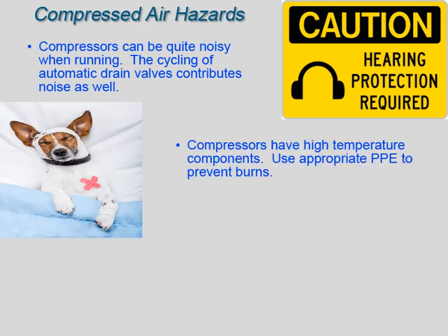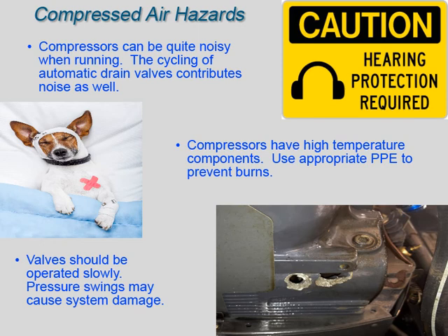The compressors, air dryers, and most piping are hot due to the heat from compression. Care should be taken to avoid contact. Approved gloves should be worn to protect against burns and pinch points. Valves should be operated slowly to minimize pressure swings in the system that may damage other components.